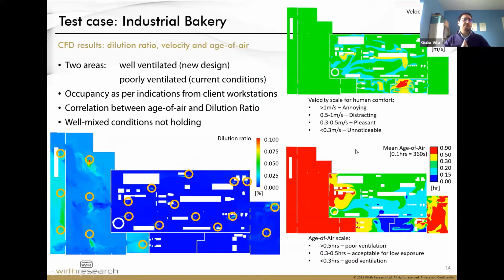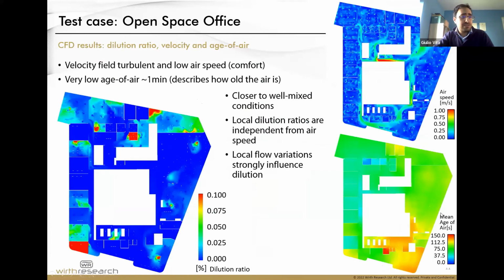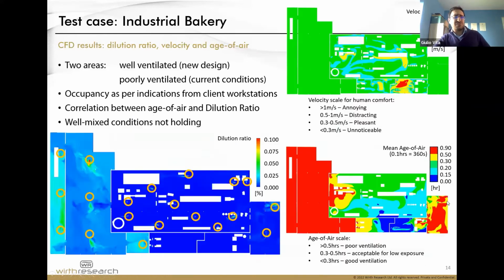If you remember the previous slide about the office, you can see that, for instance, the age of air shows very different numbers. Before we were speaking about an age of air of, if I can go back, around a minute inside the building. What we see here is an age of air that goes up to an hour and a half.